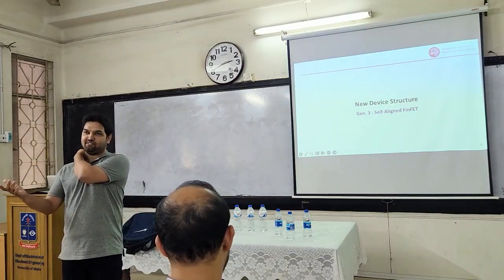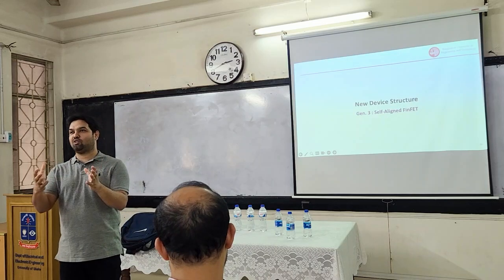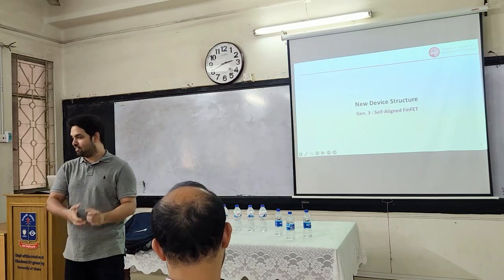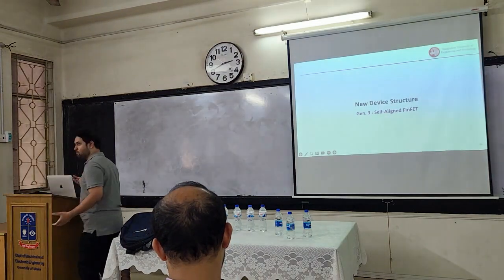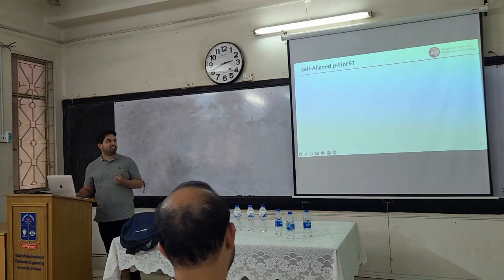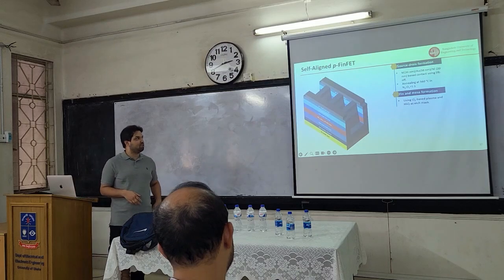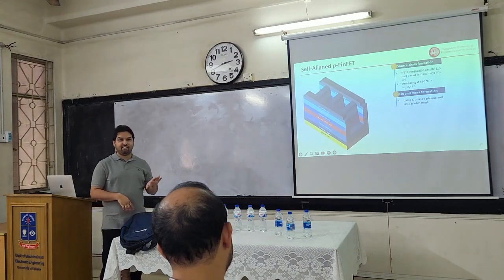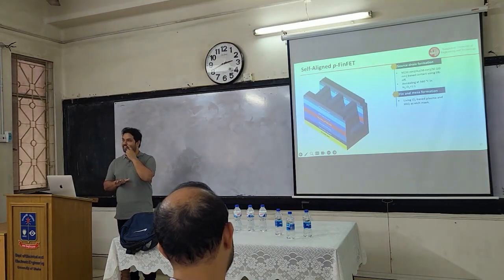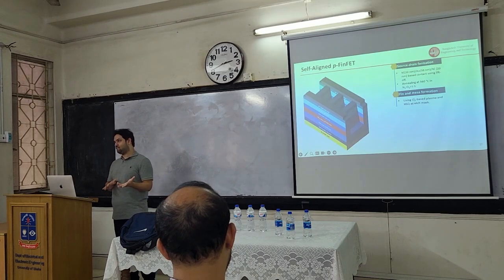So why do you make a FinFET? You make a FinFET to increase the control of the gate over the channel. Exactly the same reason people make silicon FinFETs, I'm going to make gallium nitride FinFETs. So here is the process. Basically you form the source and the drain, and then you form the fins. Even though it sounds very simple, the process development took me more than a year, because you have to etch 20 nanometer fins.